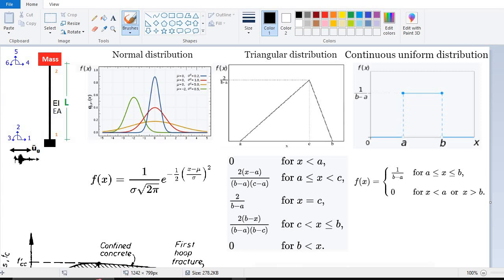and we defined element properties and strain and stress properties and also mass properties as a distribution function with 1000 different numbers between, for example, this range to this range for triangular distribution, and for these values as 1000 random numbers, and at the end we calculate the maximum absolute value of displacement, velocity and acceleration of this degree of freedom number 4.